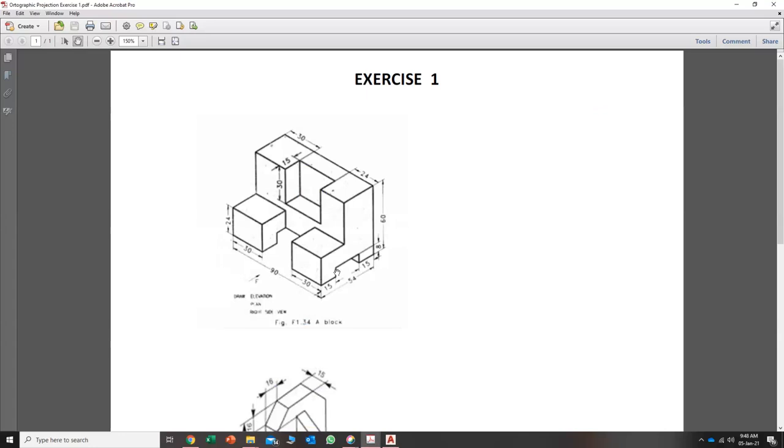In my case, 54 is the width, 54 mm for example, and the height is 60. So you know that the first dimension should be the length of your shapes. I'm going to establish this construction line.